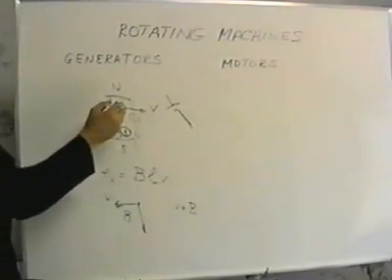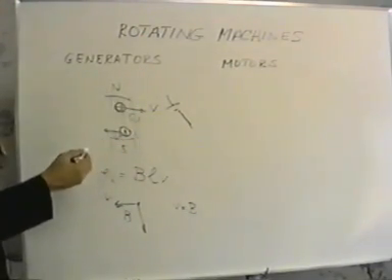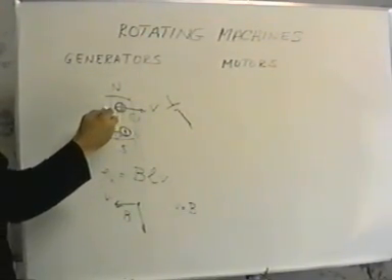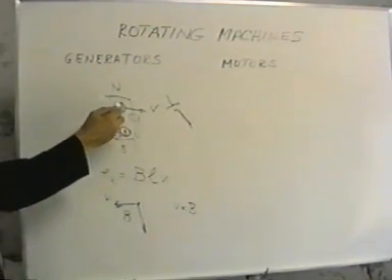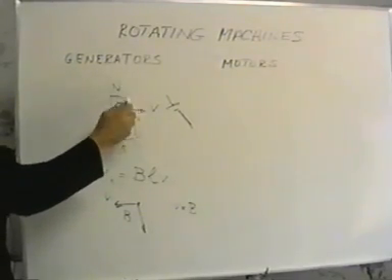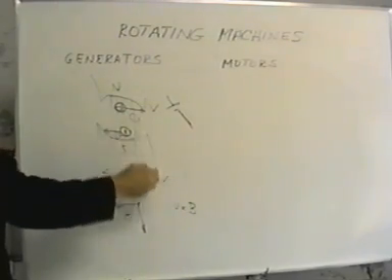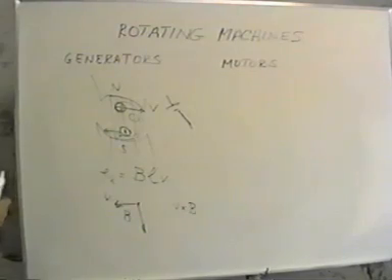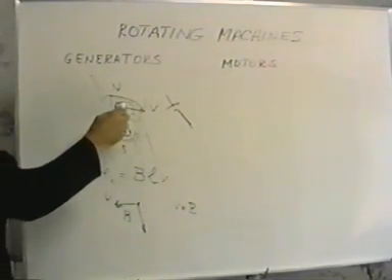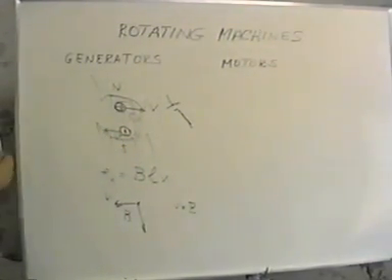So if I take this conductor and just move it once around within this air gap where we have these lines of flux, you can see I can generate a positive voltage, no voltage, negative voltage, no voltage. And if I were to stretch this out to become larger like this and more circular, as I start moving in a circular path, you can see that this voltage becomes a sinusoidal voltage. It starts from 0, goes up, hits a positive value, declines, goes down to 0, comes around here, starts to go negative, goes up the other way.